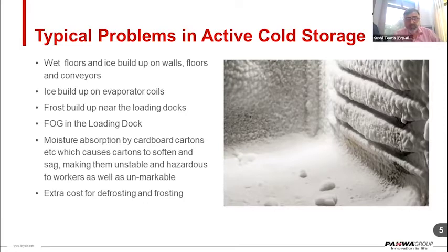So we have to stop the entire evaporative coils in between, and we have to first complete the defrosting activity there. That sometimes creates further disturbances in the entire system. And along with that, the moisture starts depositing on the product which we are storing inside the cold chain, and that is clearly visible on the cardboard contours. And sometimes some fog formation starts happening inside the room also.